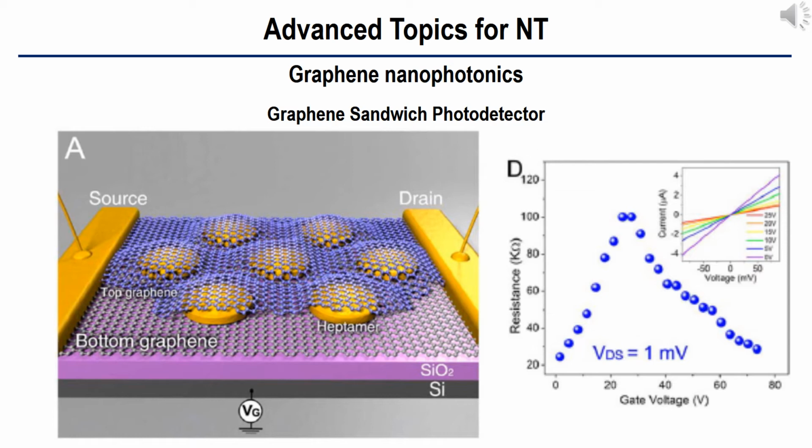Graphene-supported hot electron contribution to photocurrent is an example of field enhancement. This can be observed by direct excitation effects calculated from FDTD simulation. The smaller the antenna size, the higher the internal quantum efficiency, IQE, of the photodetector. Therefore, we can expect good performance of photodetectors by combining graphene with antennas, which extends optical sensitivity.